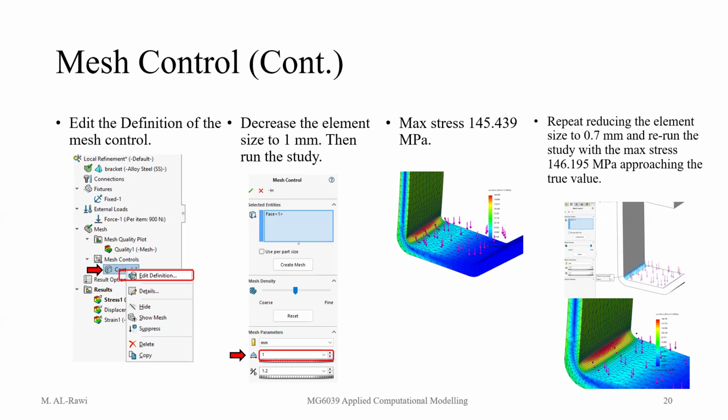So that is the other method, when you want to use a specific mesh control for an area I believe is the weakest area. Now you say, why did you choose that fillet? Why didn't you choose the top fillet or the back fillet or the other fillet? Very simple question. Because that is where the highest stress has been since we started this exercise. So I'm focusing on the areas I believe could cause me issues. The other areas I'm okay. They are behind my maximum stress concentration.